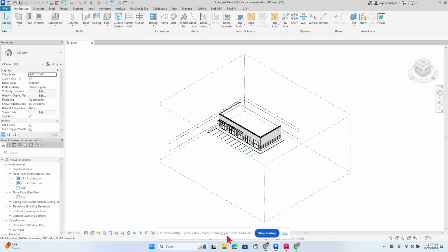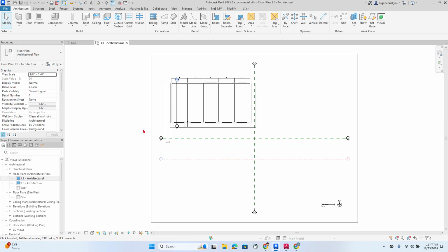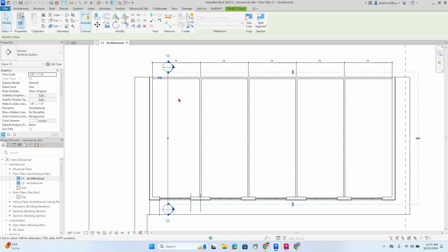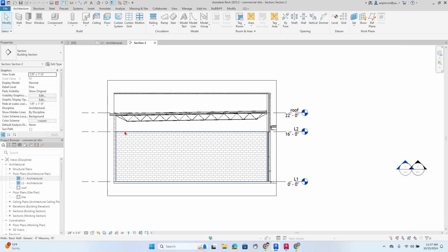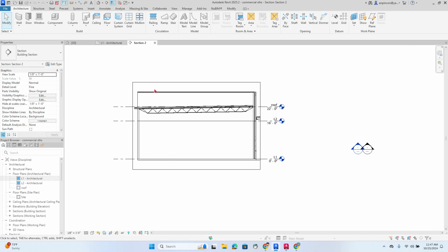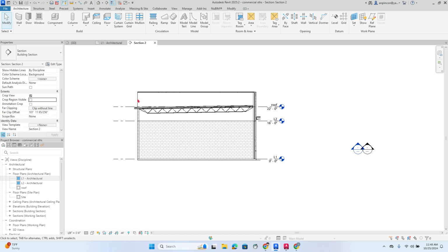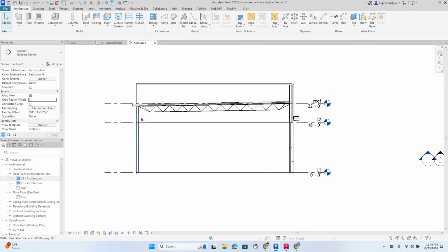Okay, guys, we're gonna work on this project here on the detailing. So let's go to level 1. We have our section, so we can double click on the section symbol. We're gonna see this, okay? We can disappear this ugly box, right? Under your properties, under extents, under crop region visible, you can disable it and apply it, and that box is gonna disappear, right?